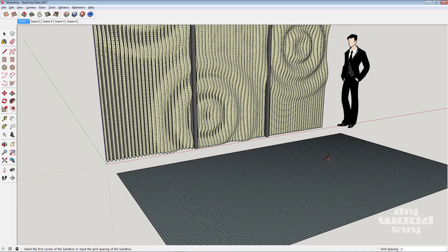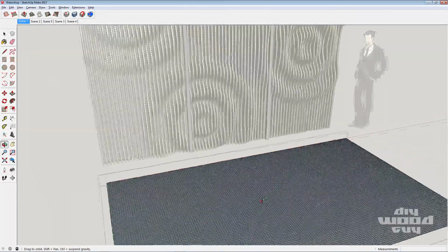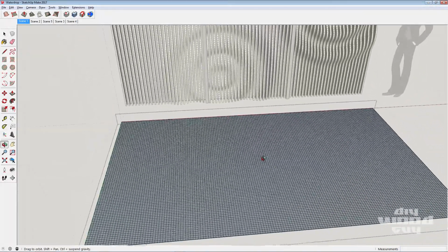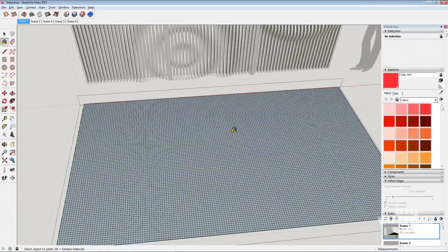You now have an array that is 160 by 96 inches. You're next going to click your Select tool and double-click on the array that you just created. Pan now to an area of the screen where you can see the whole array. Now, for our purposes, I'm going to create an array that has 3 different raindrops.